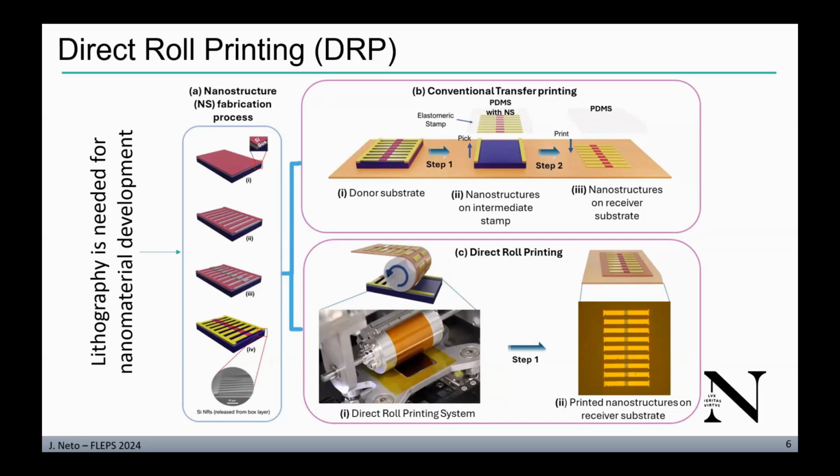But the problem with this approach is that it leaves many residues of PDMS on the surface, which are difficult to remove. PDMS is a dielectric material, and a thermal as well as electrical insulator. So when you do metallization, often you don't get a good metal contact. And that's an important part of any high performance and stable transistor response.